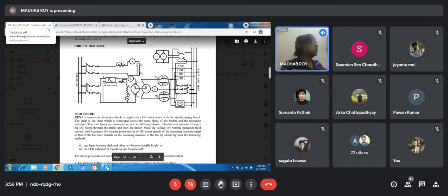Now, when we increase the loading in a synchronous machine, whether it is a generator or a motor, the alignment or axis of the stator poles and the rotor poles will show some difference. Physically, you can visualize that this mechanical degree of misalignment is measured by delta. That is reflected in the voltage phasor. We have already shown that the angle between the terminal voltage V and the induced EMF E is called delta. A similar thing happens between the rotor and stator poles.